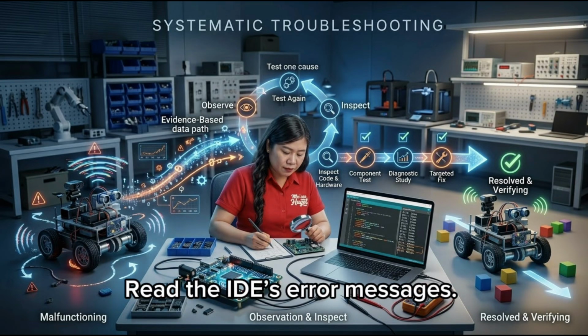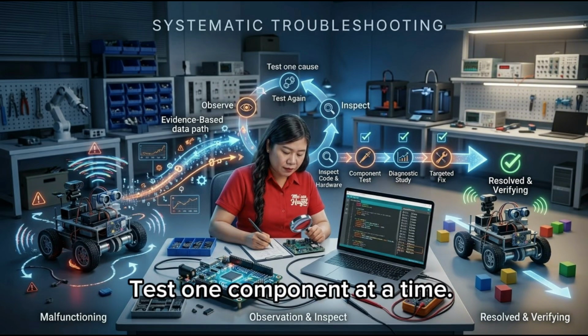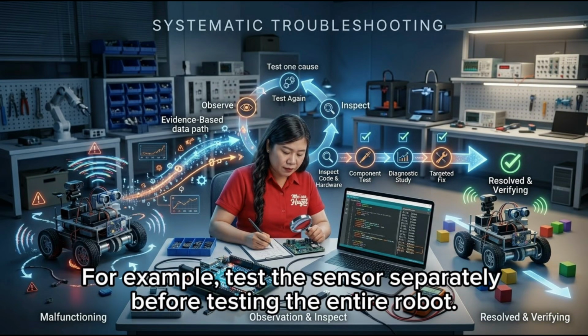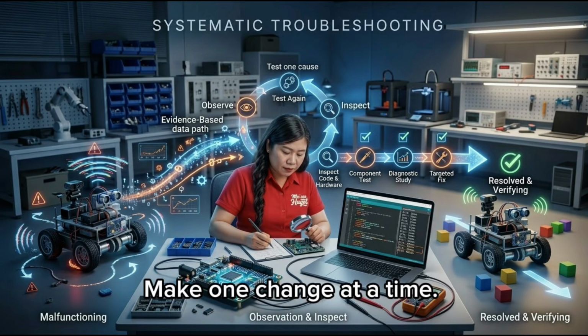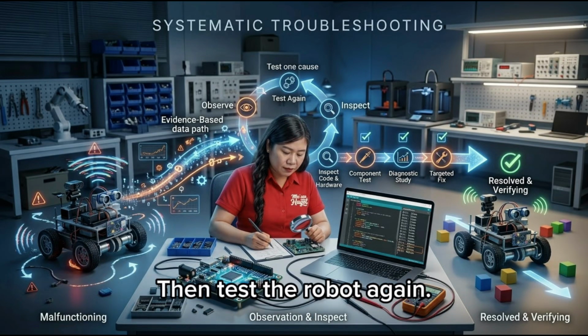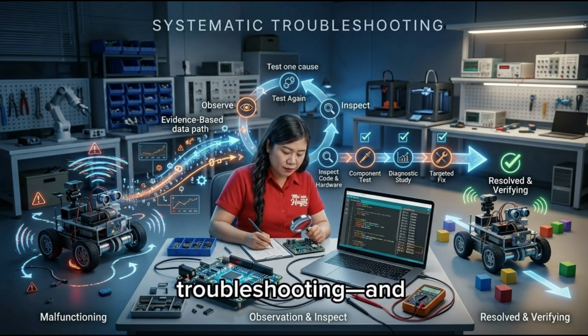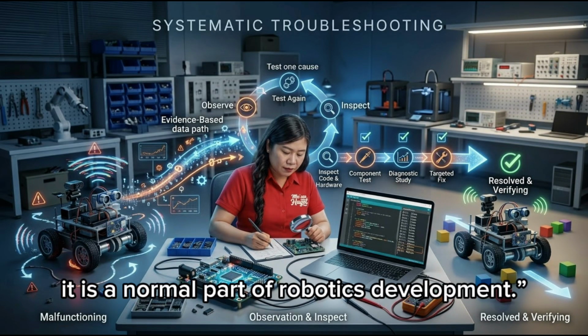Read the IDE's error messages. They often provide clues about what went wrong. Test one component at a time. For example, test the sensor separately before testing the entire robot. Make one change at a time. This helps us know which change actually solved the problem. Then test the robot again. This process is called debugging, troubleshooting, and it is a normal part of robotics development.